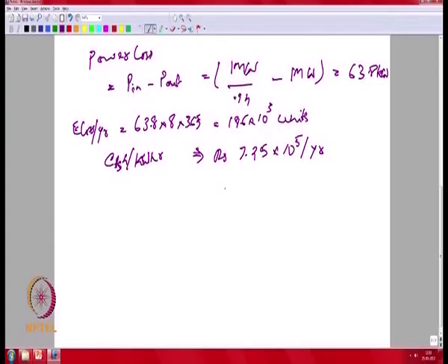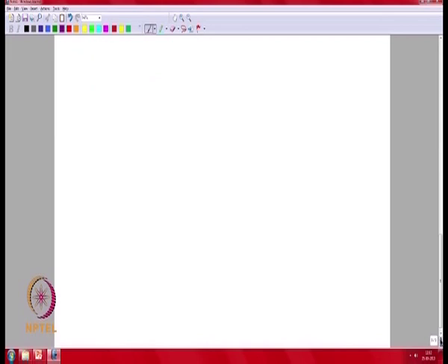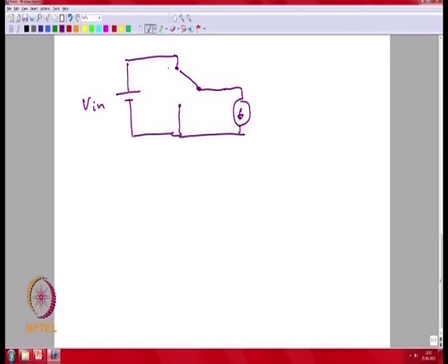So, if you look at an example, a realization of this particular circuit, in a DC to DC converter form, you have Vn. So, your pole is connected to 3, and because you are either in location 1 or location 2, you always have a path for the current I out, and because 1 and 2 are not simultaneously connected at any time, you will never create a short circuit in Vn. Okay. So, it satisfies both the conditions for the voltage source and the current source.